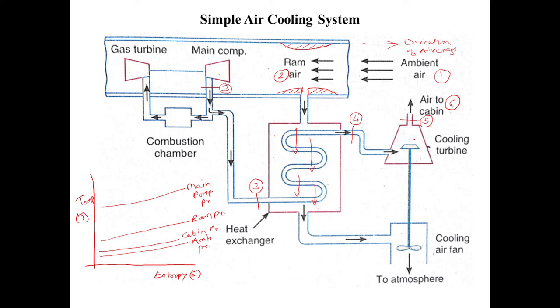Fine. Now there is no need to draw any more lines for the pressure, as all the pressure lines are already drawn. Now we'll go on plotting the various points, because we have a total of 6 points. Let's see how to plot those points. Starting with the cooling process, I will start from the right hand side. The ambient pressure is point number 1, so point number 1 will definitely be on the ambient pressure line. Somewhere over here I am showing point number 1.